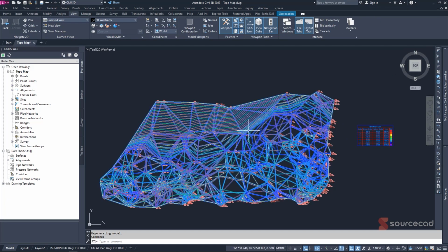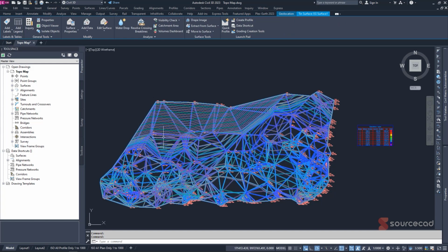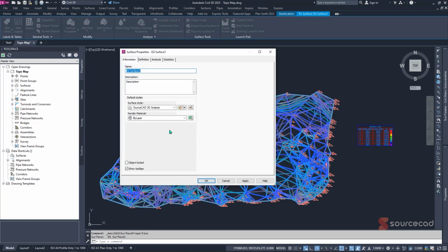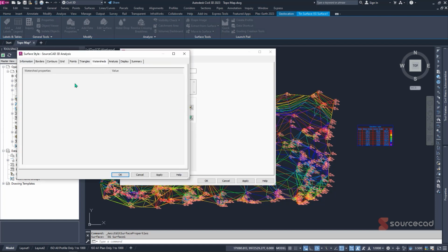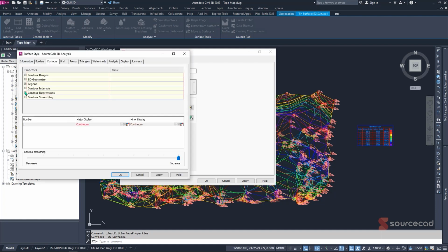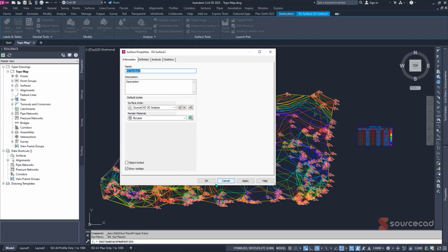That being done, I just want to place my simple annotations so that I see how the contours are moving, and I actually want to even change the intervals of this spacing within my 2D. So to do that, I'll simply edit this 3D layer that we had placed. I'll click on this, edit the current one, and under the contour intervals, we just want to confirm that everything is all right. So everything seems to be okay, that we have our minor at 5 and our major at 20. So that's okay. I'll click on OK and leave it as is.